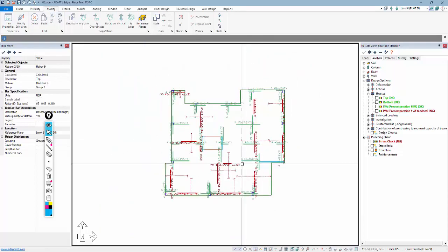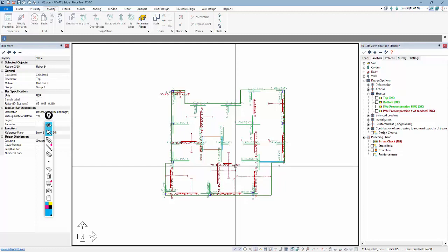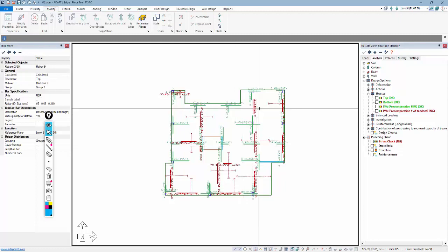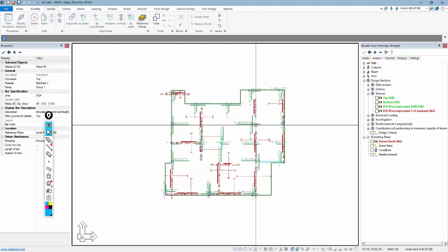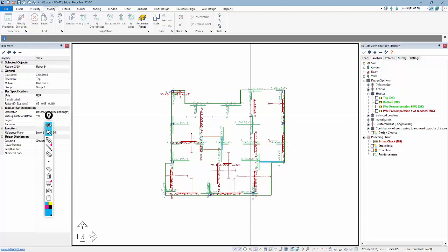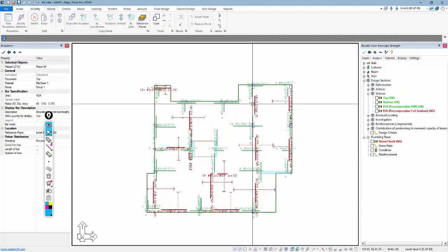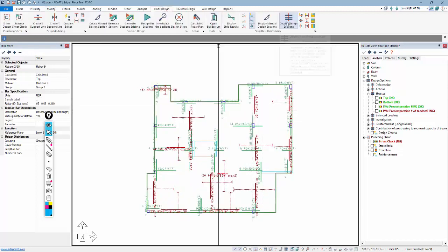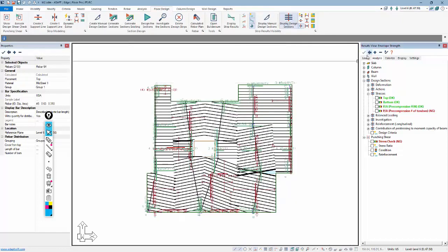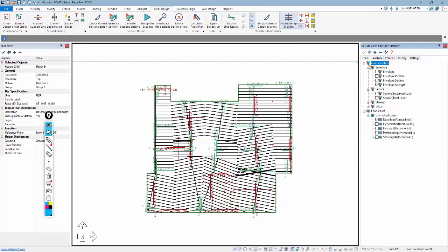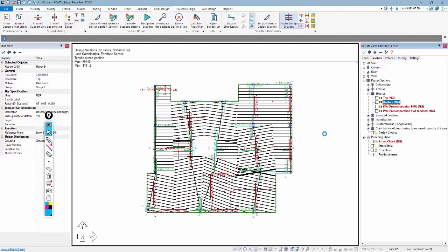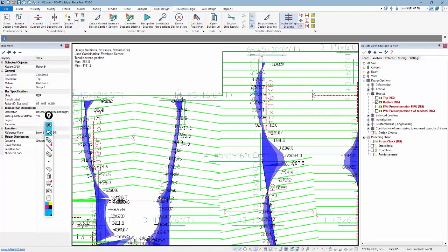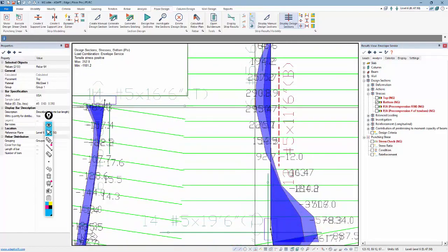Okay, so this is the output for the minimum requirements for that slab, and all of these bars correlate back to a design strip. They're all based on a strip. For example, this 12 number 5s here at the bottom, if we go back and look at the Y direction strips and I look at the stress for, let's say, envelope of service, the bottom stress, the maximum is around 295.